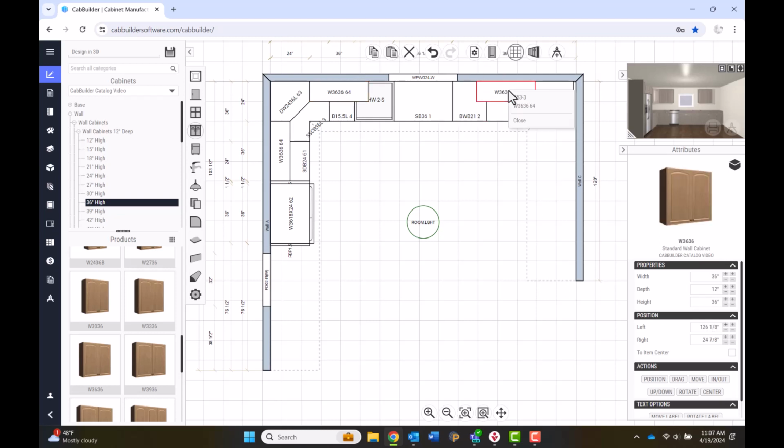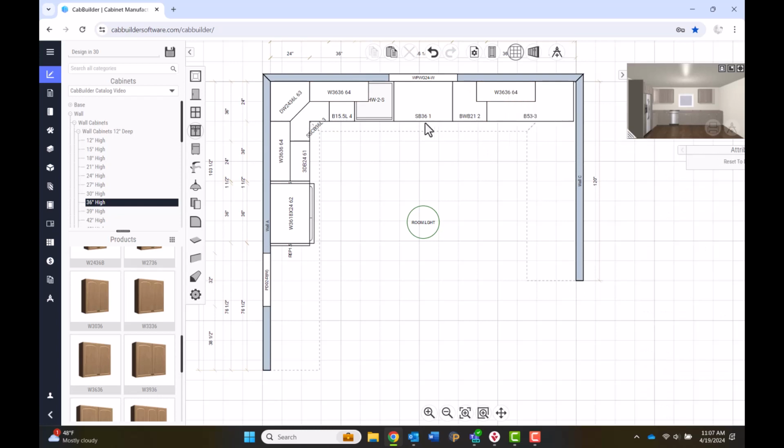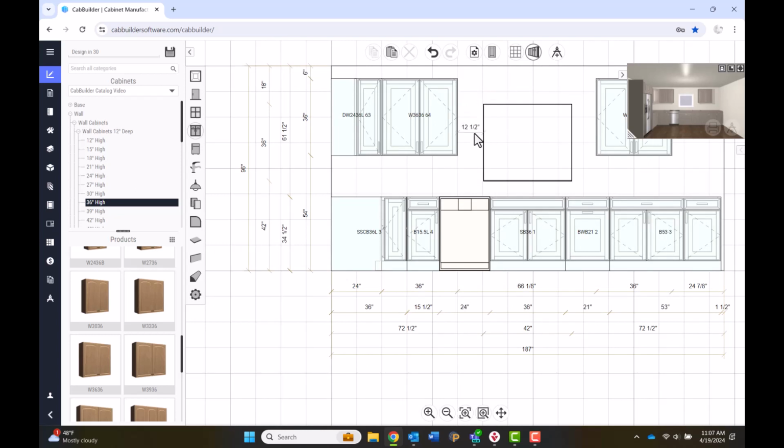Once the bases have been placed and you are working with your upper cabinets, if you need to determine distance between wall items, you will need to navigate to the elevation view, which are automatically created for each active wall zone. Navigate to the top of the design view and click the elevation icon. This will provide a drop-down menu with the available wall elevations. Select the appropriate wall view. Hover between the items to see the distance between.